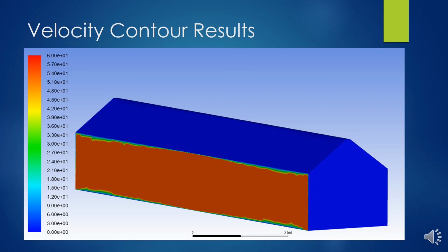The only thing I added was, for the cell boundary, I added the air constants, and for the boundary conditions, I added the inlet speed, which at first was 120 miles an hour, and for the next one, after this, was 90 miles an hour. Also, I assumed 9.8 meters per second squared for gravity and 97,200 pascals for the gauge pressure that day.